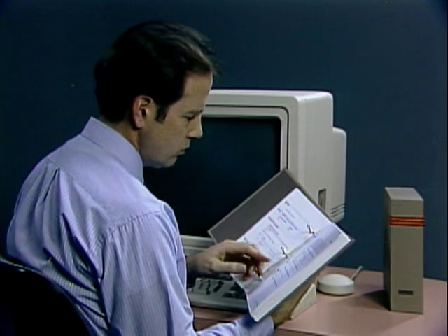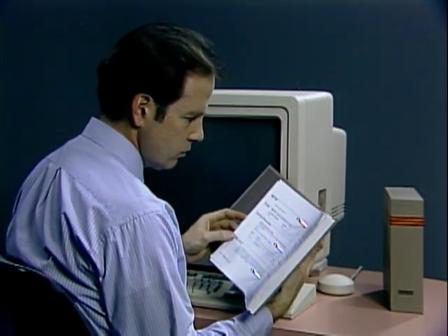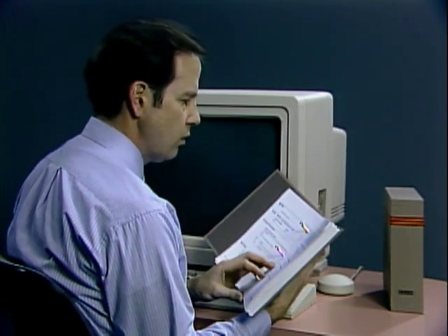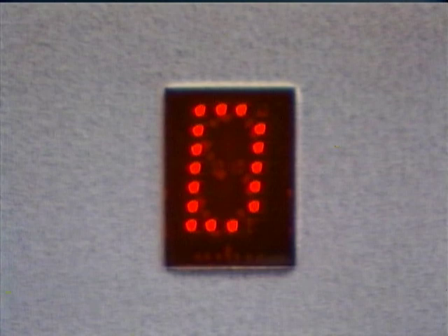The countdown is displayed on the LED display on the I/O cover, and the console terminal screen remains blank while this section is being run. Any failures encountered during this initial check will cause the test to hang. If you encounter this symptom, it is usually caused by a faulty CPU. However, it could be caused by something else, such as a faulty I/O or graphics subsystem.